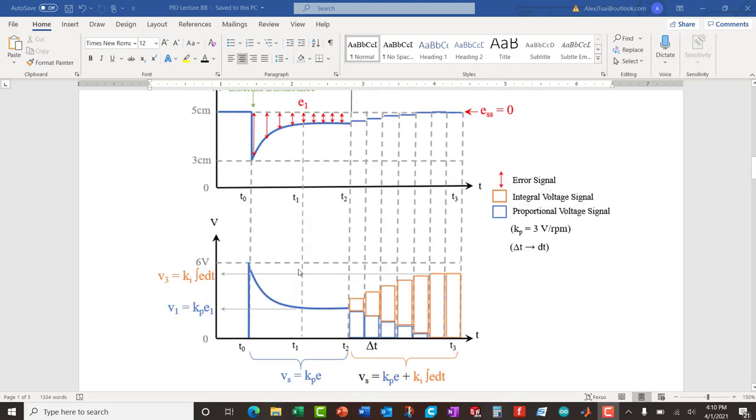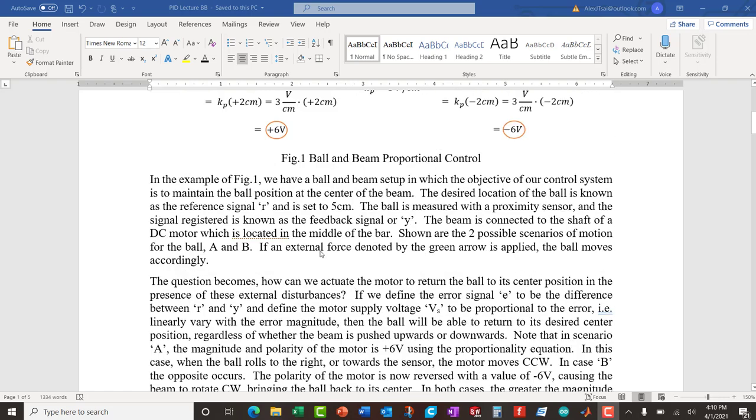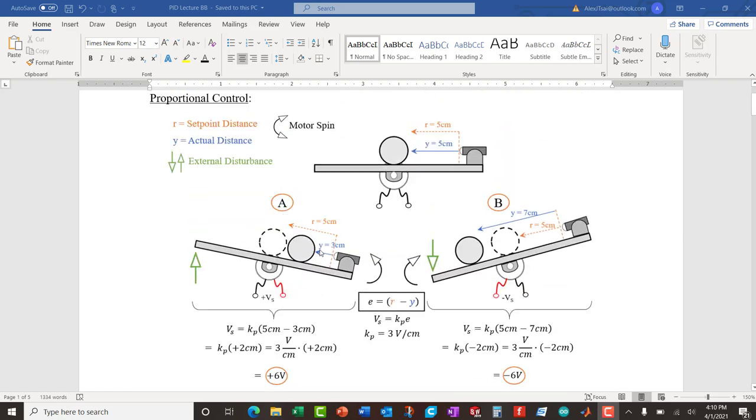Okay, just by testing the system, throwing some signal in there and measuring the response, and just from that we should be able to get a transfer function. Very interesting topics. It's called system identification, and there's a great variety of literature out there on different methods in which to get this. Okay, so we're going to be talking about tuning rules, which means how do I get KP, KI, and KD without doing all that math.